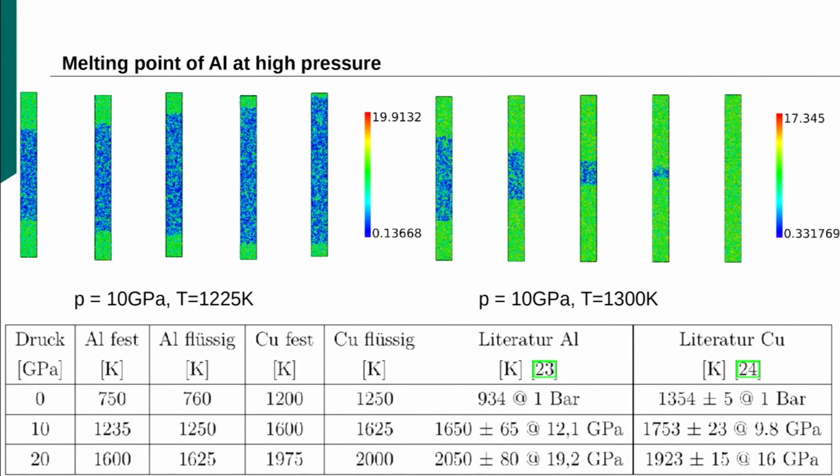So what one would conclude here, if you believe the temperatures, this should not lead to melting at these conditions, because the pressure is too high to allow for a melting. But again, I would say we're very far out of equilibrium, so you have extremely high defect concentration, you have all these partial dislocations or stacking faults or so, which can lead to a lowering of the melting point or to a destruction of the lattice structure here.